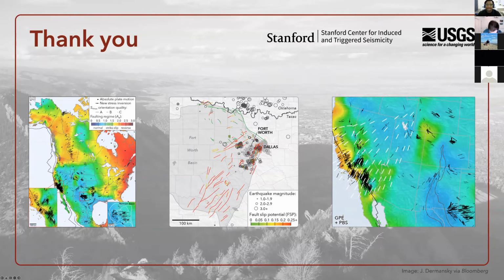As I started to say during the presentation, it depends a lot on the quality of construction in the area. Ultimately, it's a matter of the type of construction and the surface shaking, or the type of ground motion that occurs in that area. In some places, a magnitude 4 earthquake could be very concerning. In other cases, it may not be, depending on where you are. So that goes beyond just the magnitude of earthquakes into the shaking.